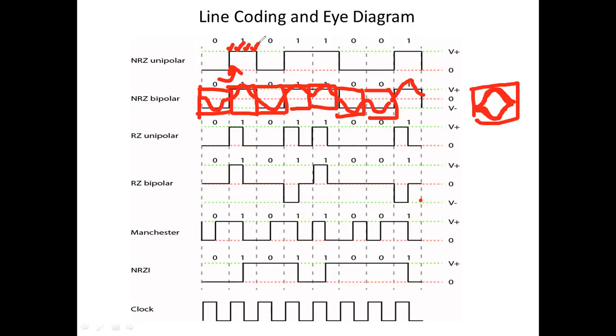Okay, but in the case of an eye diagram, in case of a raised cosine, you realize with this particular eye diagram, you want to go for an area where the width of the eye is maximum, right? So if I want to sample this, probably the center of this eye would be an ideal choice.